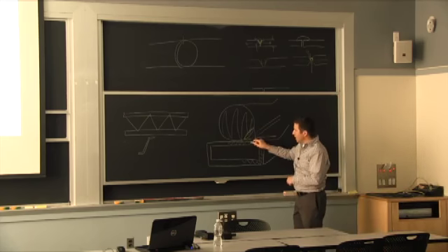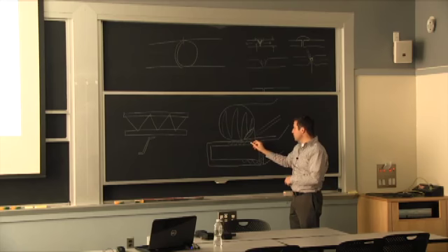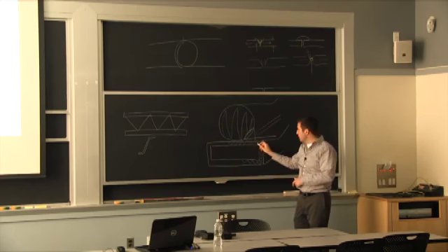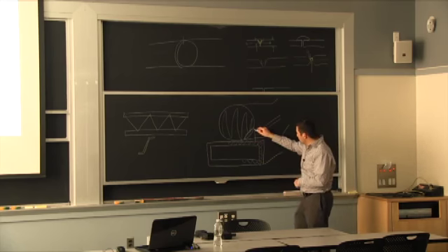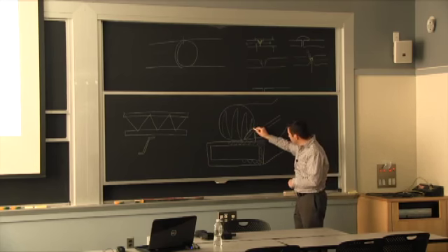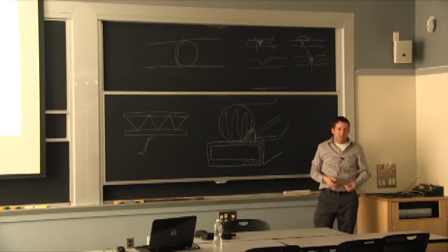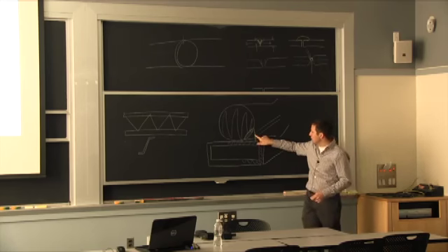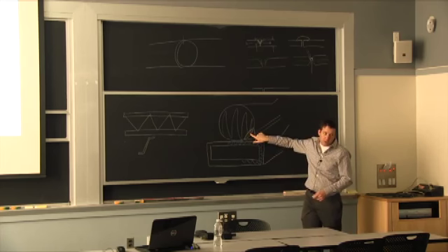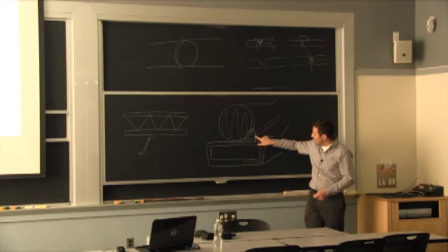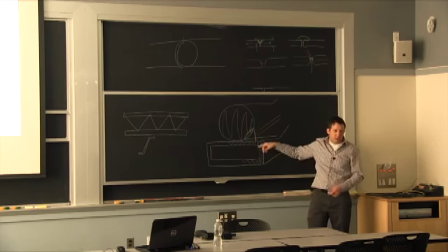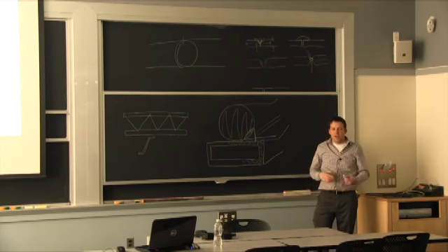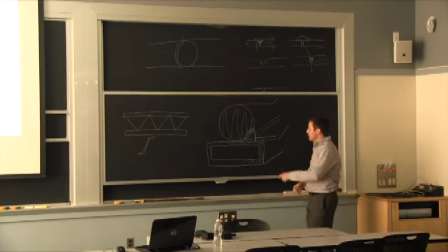In this case, we do want to add metal. One of the reasons is we don't really have too much metal in the first place on this tubing. So by adding the metal, you're only going to melt a certain amount out of each component, hopefully. And that's where the skills come in as far as controlling the arc, so it doesn't always stay on the same part. The arc on a geometry like this will tend to be trying to go in one direction against the mass, and you have to weave a little bit to get it on the other side. It's just not the easiest weld to make. You know, I'm taking this as the extreme example.